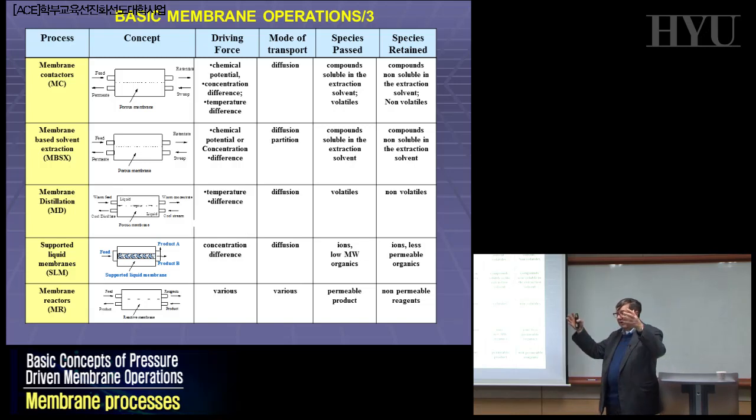That means if you make a reactor with the wall in palladium, theoretically, any production of hydrogen during the steam reforming, for example, during the reaction, you form hydrogen, but this hydrogen will not stay in the reaction zone, will move across the membranes and will be continually separated from the reaction zone, which means, if you remember the Le Chatelier principle, or just this basic equation in chemistry, if you continually remove one of the products, any reaction will never reach equilibrium. Any reversible reaction is becoming irreversible.